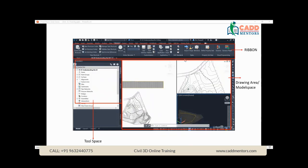And when it comes to Analyze, this will be useful for you. You did your entire design, and you want to check your earthworks, how the cut and how the fill is coming, how do you compare them? And when somebody asks you what sight distance is achieved in the particular road that is being designed, those sorts of analysis, Analyze will be useful. As you can see, it has visibility check and those things. So like that, you have many things.